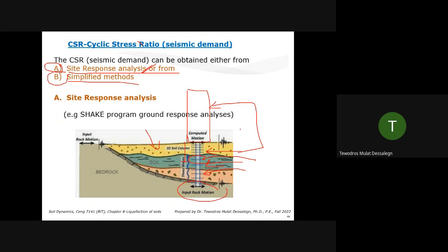In some cases, research cases, you may even model the water inside the soil. Now you're modeling liquefaction. If you are using saturated soil, imagine you have, let's say, loose sand, and a structure. So you're modeling actually a realistic case, like a liquefaction case. But for now, let's focus. Assume no structure here. It's ground only. We are doing ground response analysis.